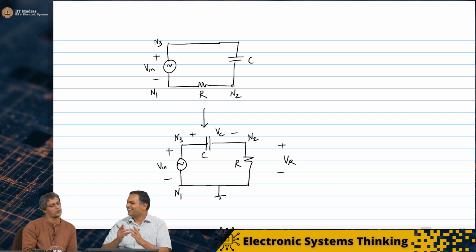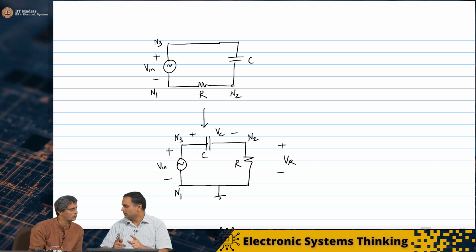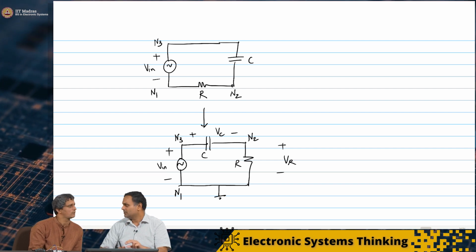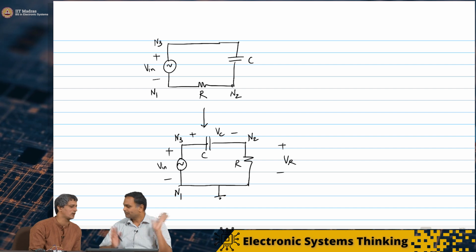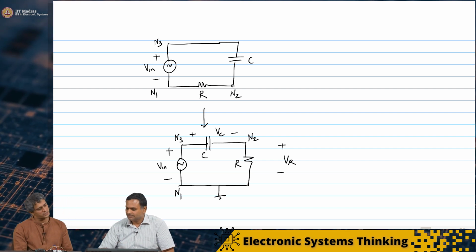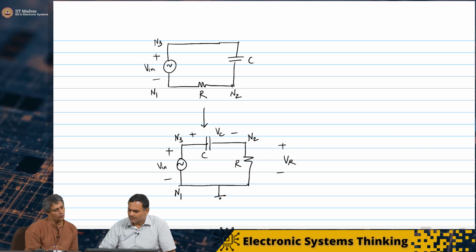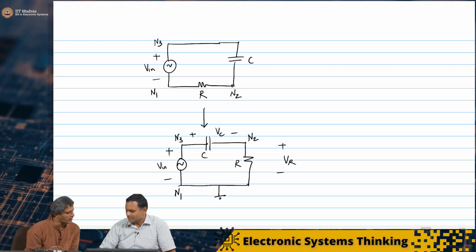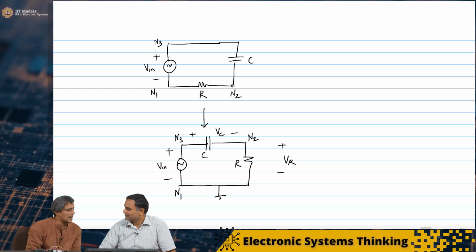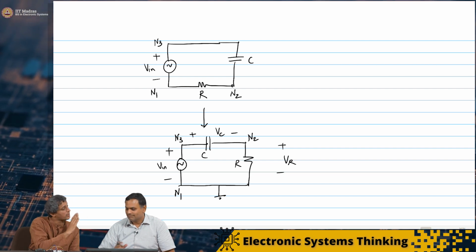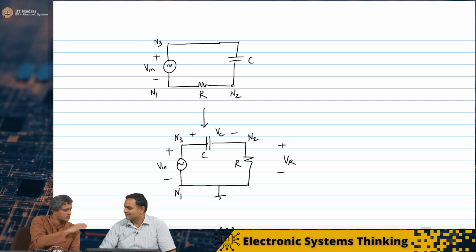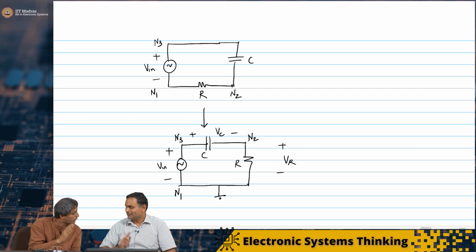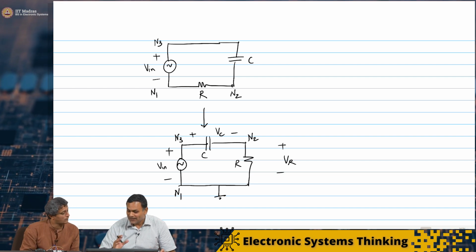Because the circuit is exactly the same, we have just done two things: applied the superposition theorem, applying the negative of the voltage, and redrawn the circuit a little bit. So if we now look at a circuit on the breadboard and do the exact same experiment as last time, keeping the amplitude fixed and sweeping the frequency, we should see the behavior of a high pass filter. Let us do that now.